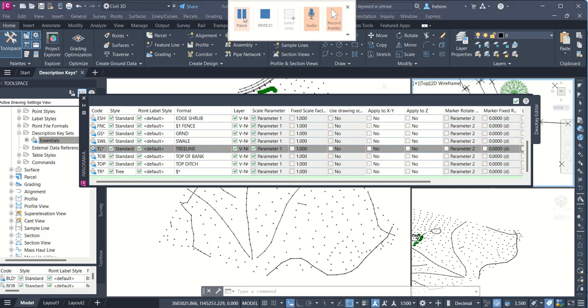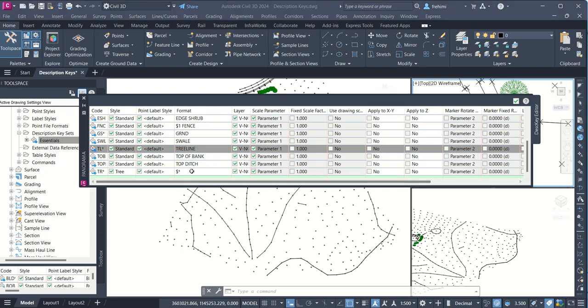So these are styles, okay? These are text styles. In the text style, the text style is a vector. You can, I think, go until 13 descriptions in the column of description keys, the last column of your text file. So if you see, for example, here, what is mentioned by default, dollar star, means write everything you have in the description.